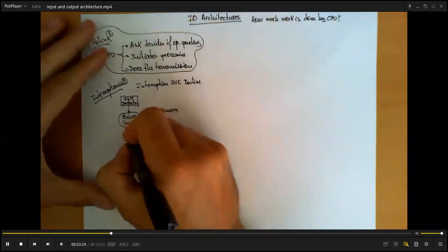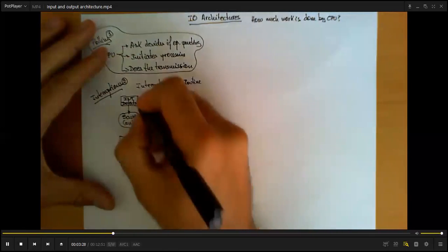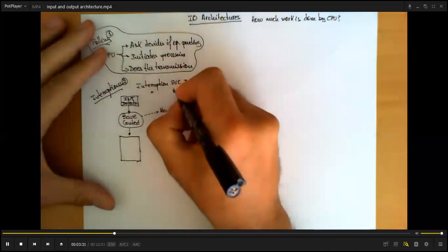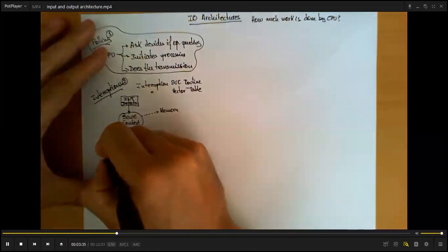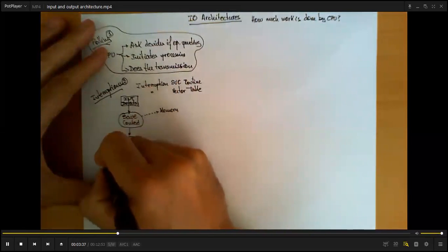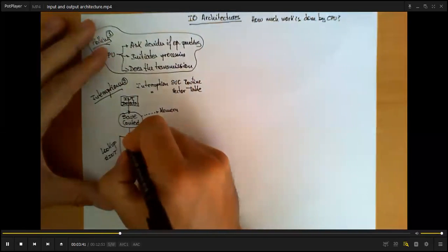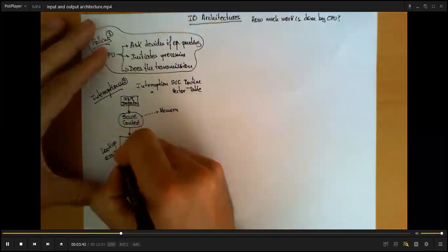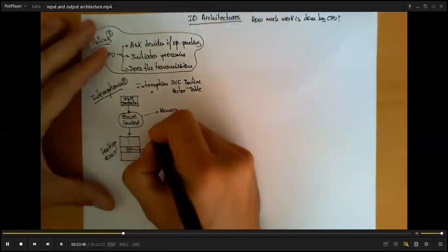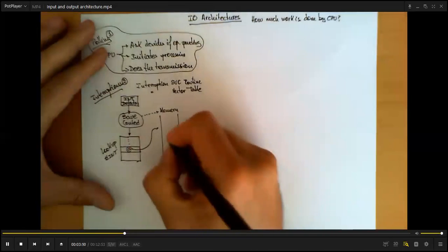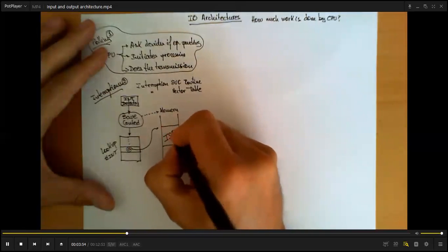Now the next step is one of the most important ones. There is a table which is checked. This table is called the interruption vector table, and it is used to perform a lookup operation in which we use the number of the interruption that was received by the CPU. The lookup identifies one slot, and each slot contains the address in memory in which the interruption service routine is stored.